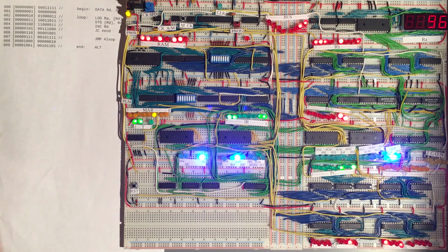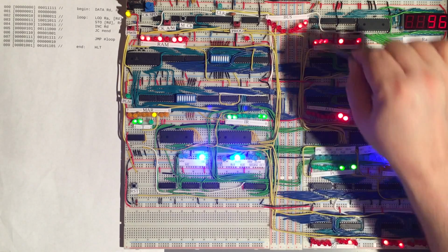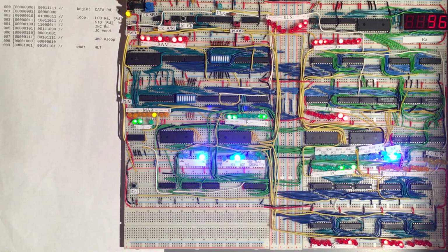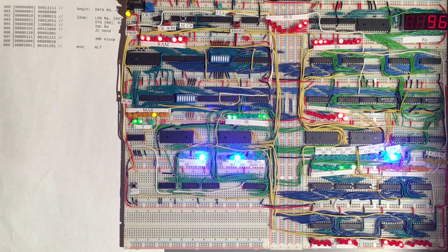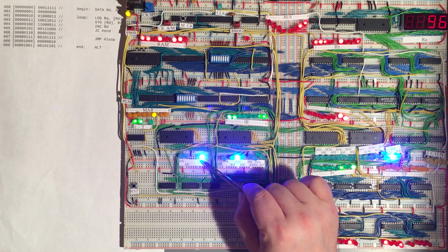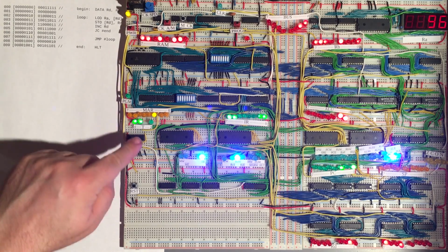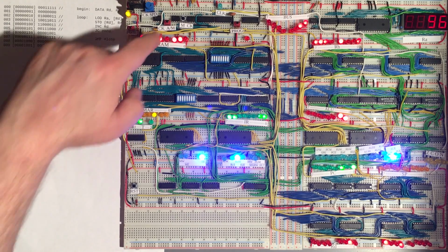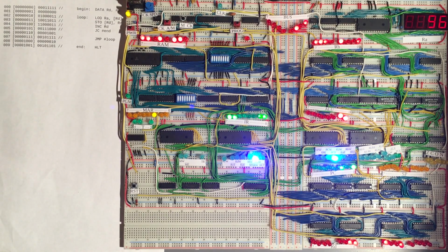And since we're increasing a register into itself, we then need to assert the write signal for this D register so that the contents of the ALU will be written back into the D register. And this is the final step which we need to perform in order to complete this increase instruction. We also have the timer reset signal here, which is asserted. And so on the next rising clock edge, we will complete the increase instruction. And so there we have this 3 now.